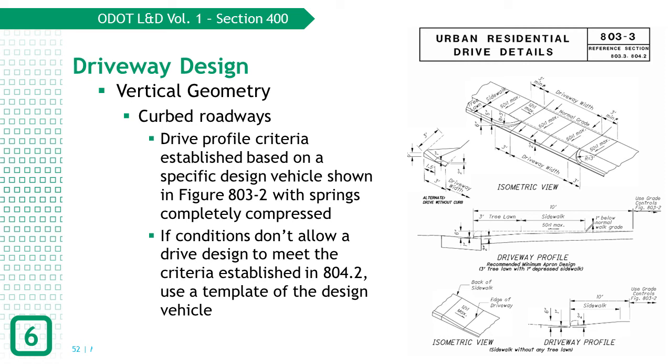The presence of a tree lawn forces the driveway's vertical grade to increase to meet the sidewalk elevation, which is typically vertically above the gutter elevation by the height of the curb. Without the tree lawn, a parallel ramp is placed in the sidewalk approaching the drive to lower the sidewalk to one that is closer to the gutter elevation.